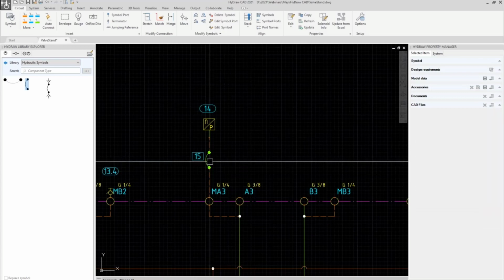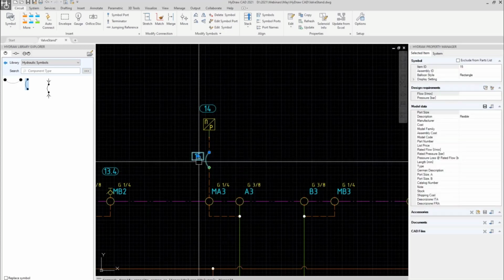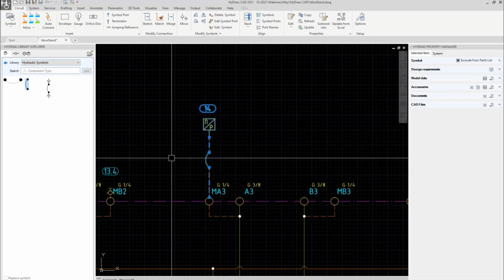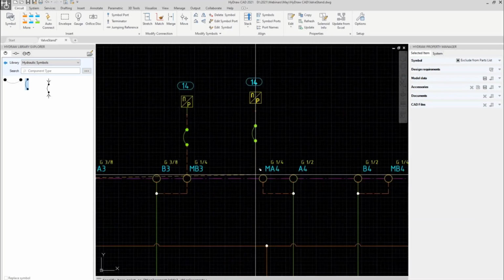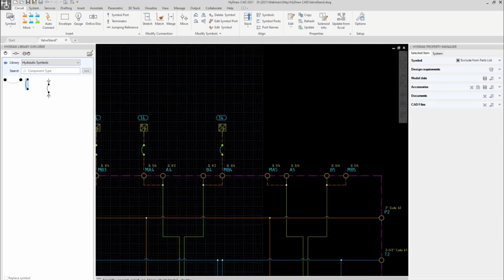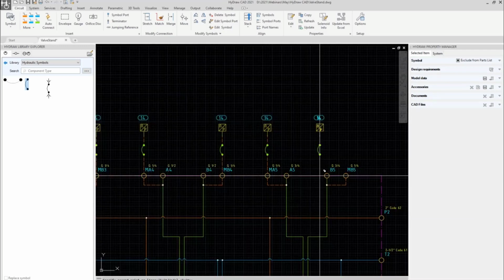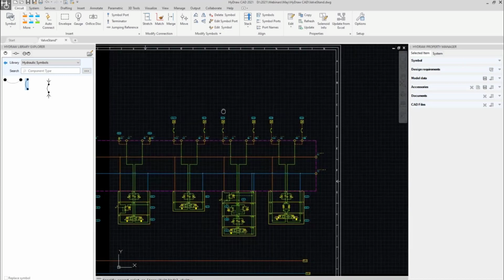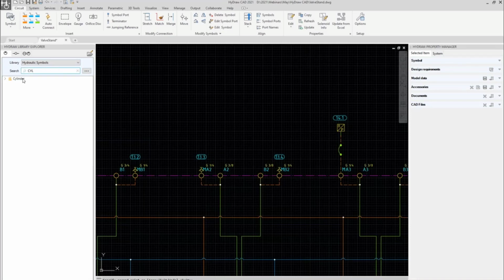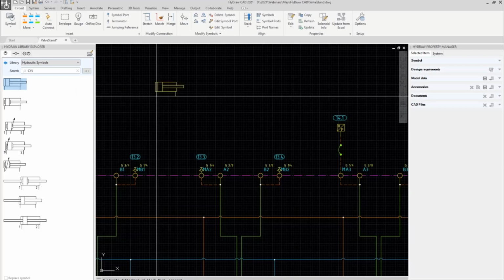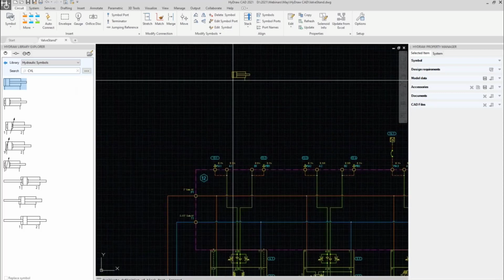That's fine. Now, let's say that I don't want the hose to be in my part list, so I exclude from part list, and I just do a copy. Let's say that between my valve and my actuator, which I'm going to place, so let's look for a cylinder, double acting, and I place my cylinder here.